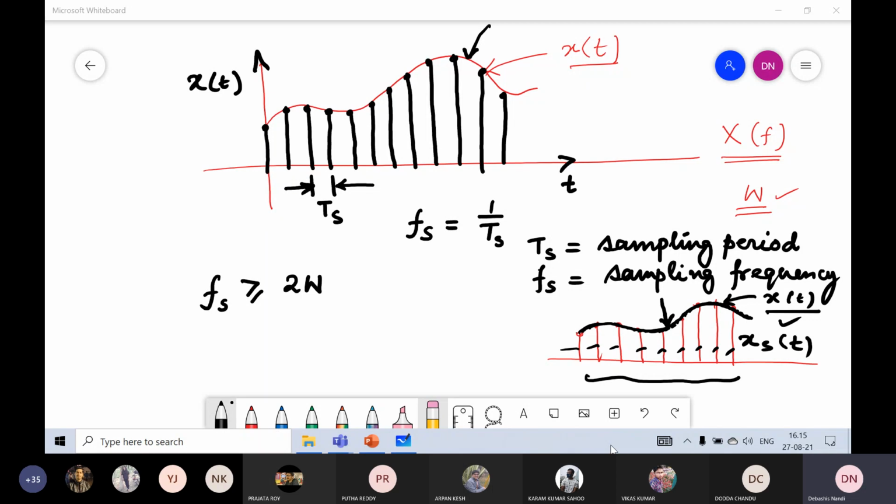So the microphone output will be the electrical image of the sound signal, and that is a continuous time signal. If you want to store that song in your digital device, then you have to pass this signal through a number of stages to convert it into digital format. The initial stage is to filter the signal, because some noise may be there in the output of the microphone. Then you have to magnify the signal by using some amplifier.